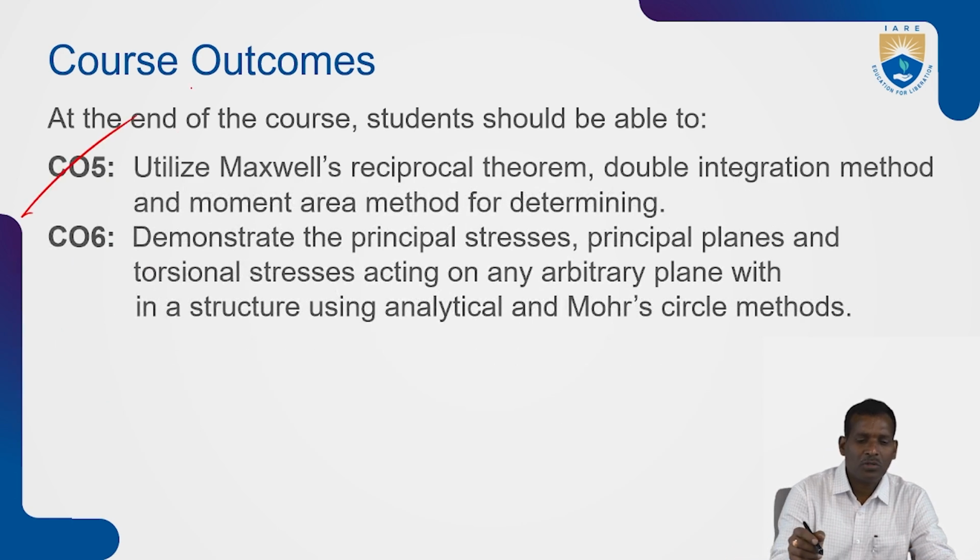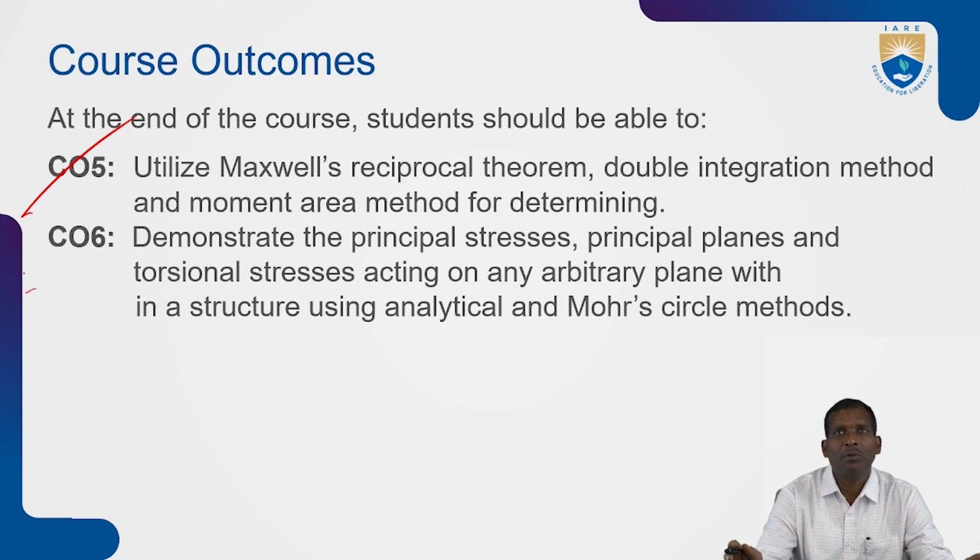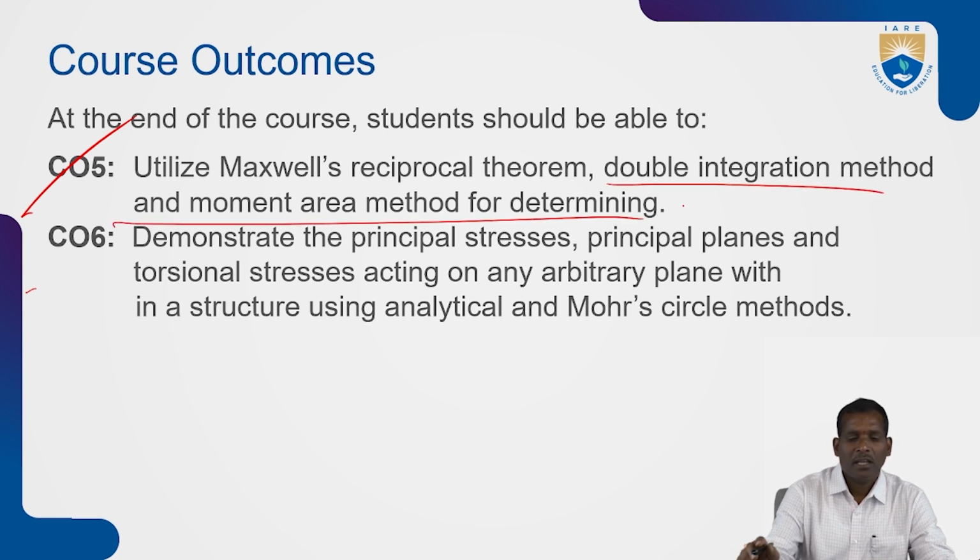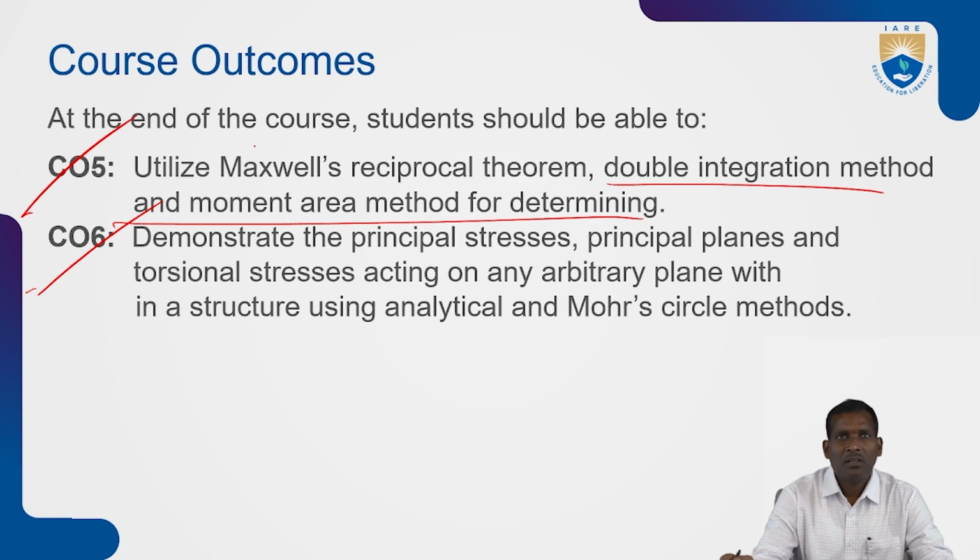At the end of the course, the student should be able to utilize Maxwell's reciprocal theorem, the double integration method, and the moment area method for determining deflections. CO6 is to demonstrate the principal stresses, principal planes, and torsional stresses acting on any arbitrary plane within a structure using analytical and Mohr circle methods.